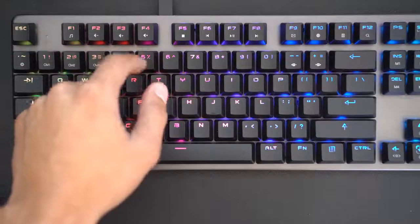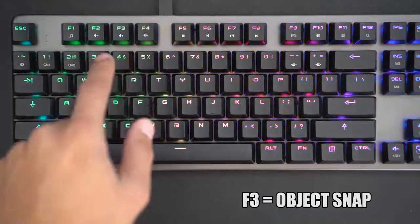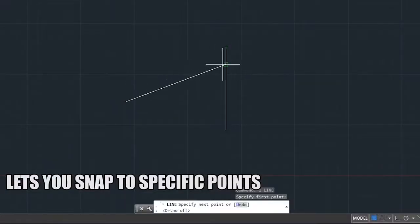The first command is F3. This function is called object snap. Basically, it lets you snap one end of your line onto another end of a line, or middle of a line, or to a perpendicular area. To put it simply, it kinda magnets one point of your line onto another key point of an existing line.